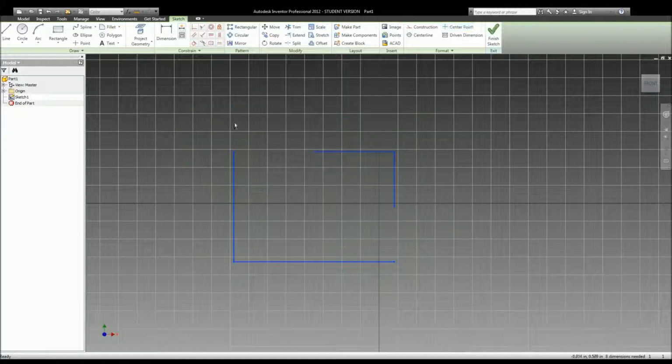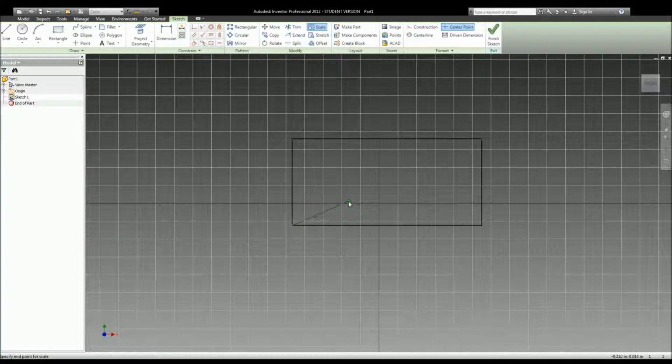You can actually scale the whole thing if you wanted to, clicking all of the sides and then clicking the point that you want to be seeing the increase or the direction that the scale goes. Okay, so I'm going to say this point here, and it becomes the base point. Sorry, I mistakenly said direction, point, so on, but yeah, I meant to say the base point as the prompts specified. Okay, so that's the scale function.